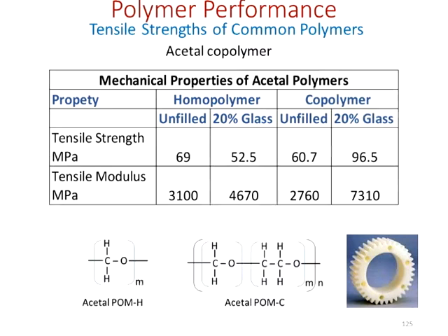That tells you there are interactions in the copolymer that are different, and the way it compounds in and mixes in is different. Keep in mind, this is a mixture, and you're trying to mix this in a fashion. They're heterogeneous. They don't dissolve into each other. They basically mix with each other, and they interact, and the interaction for the copolymer with the 20% glass is different. Likewise, the tensile modulus for the homopolymer with 20% glass is less than that of the copolymer, and this